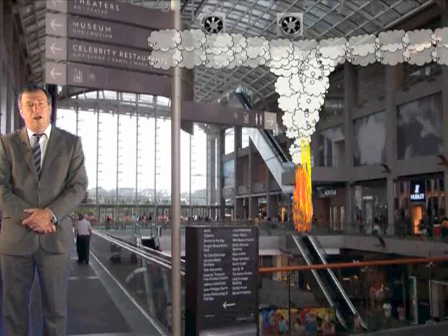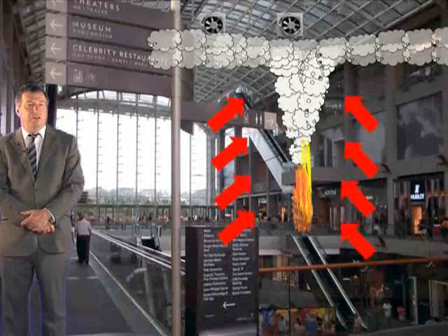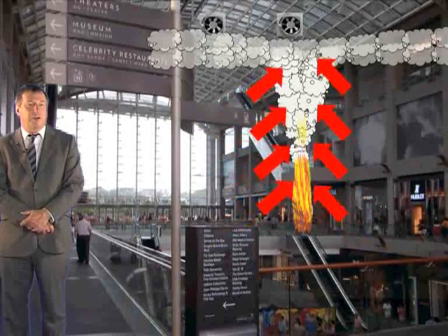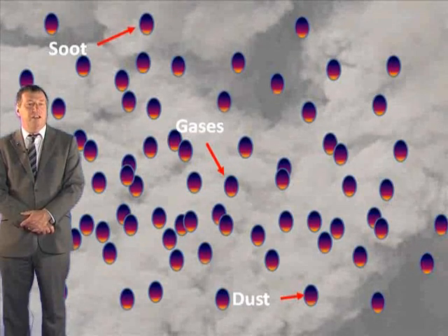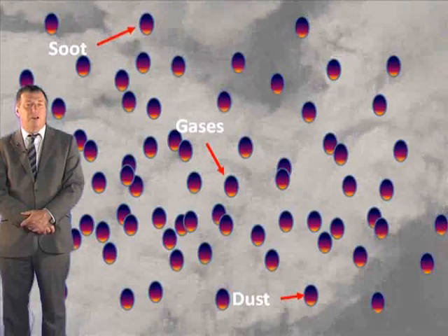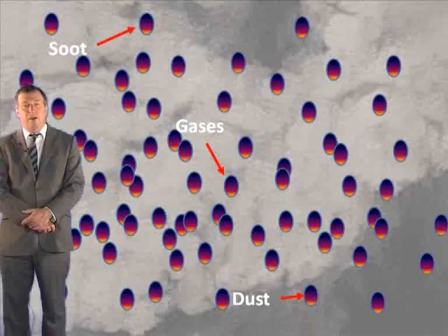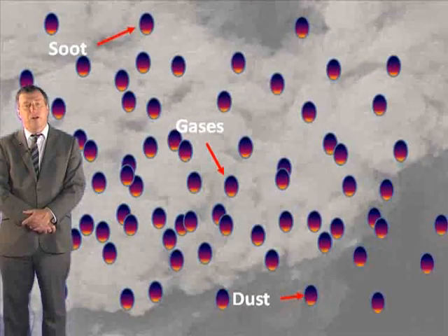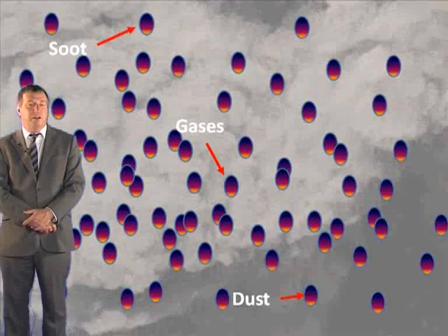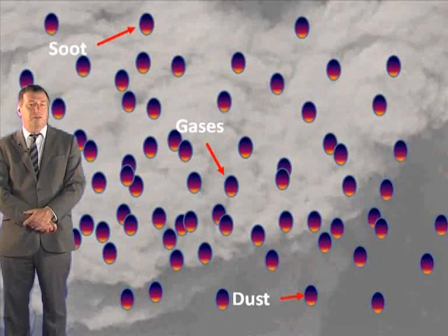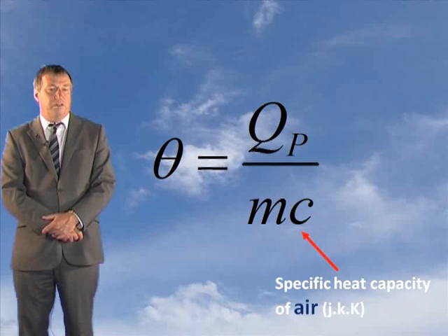Let's have a look at how this equation works. Firstly, why do we use the specific heat of air when it's smoke that we're examining? Well, the reason is simply that smoke is virtually 100% air, heated and dirty air, but air nonetheless. Most of the mass flow rate that we calculated earlier is entrained air, and only a very small proportion of the mass flow rate relates to the soot and dust and particles and gases that are actually emitted by the items undergoing combustion.